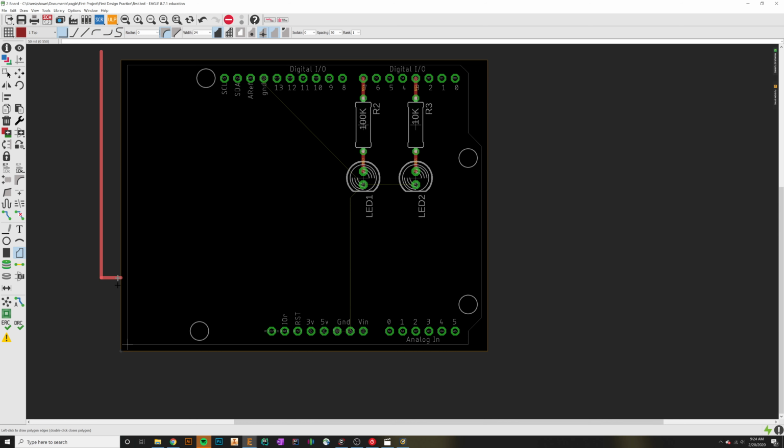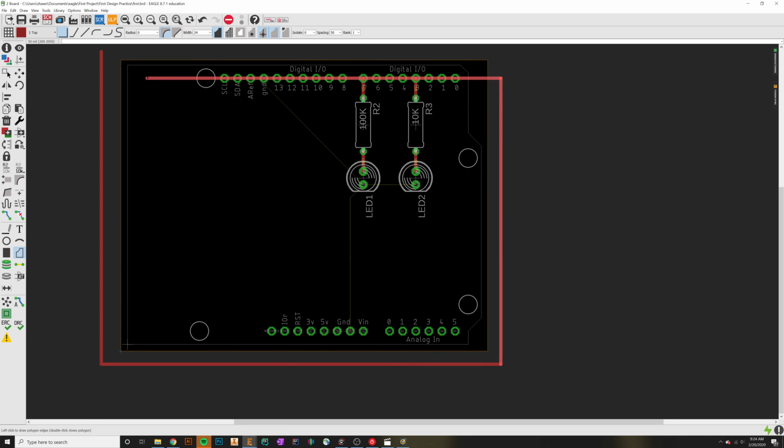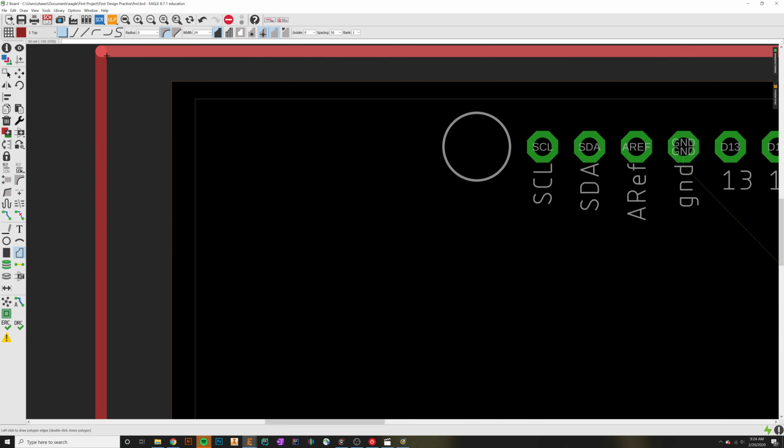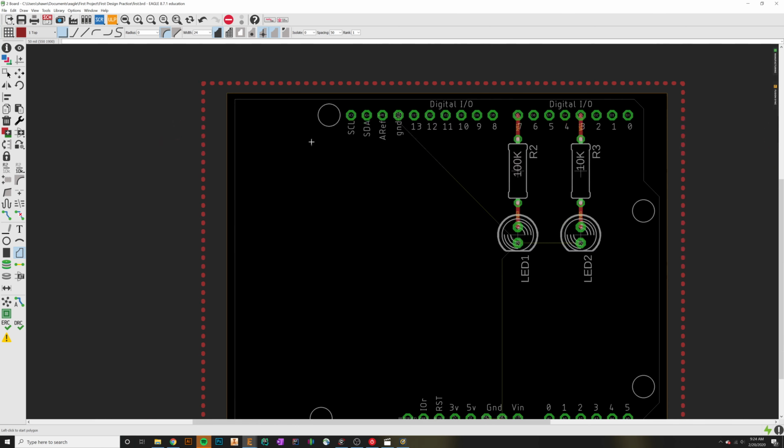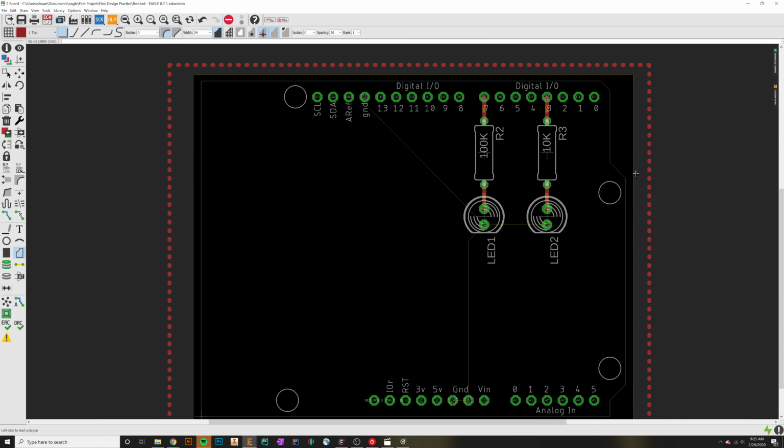And I'm just going to keep right clicking until I get this option here. You can manually just click this right angle tool. And I'm just going to go ahead and start to come around up until I can complete this little line here. And you're going to see that if it's still a solid line, that means you did not connect it together. But if you get a dotted line, that means you were able to make a full connection back.